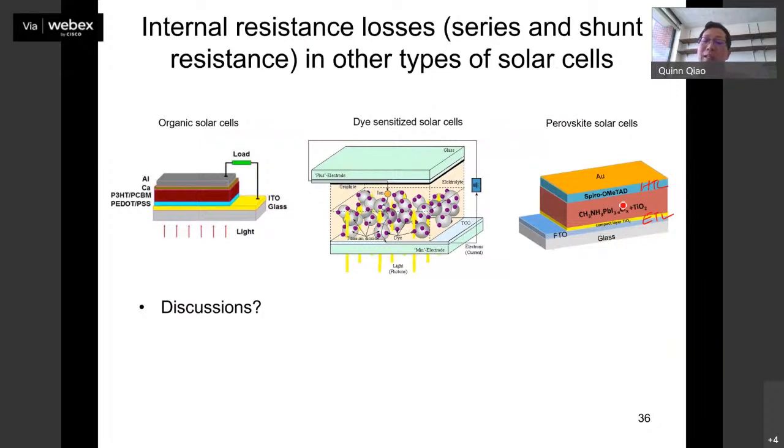And then for the perovskite, you don't want to have a lot of grain boundaries to trap a lot of electrons and holes there. Then, you increase the crystallinity, the quality, and also the uniformity of the surface of the perovskite. Also, when you grow the perovskite, you want all the precursor to fully grow into the perovskite. You don't want to have this PbI2, SnI2, this kind of thing there.